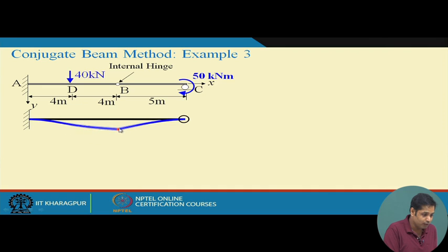The deflection is continuous, and the slope is continuous up to this part. For part BC the slope is separately continuous, but at point B the slope is not continuous.